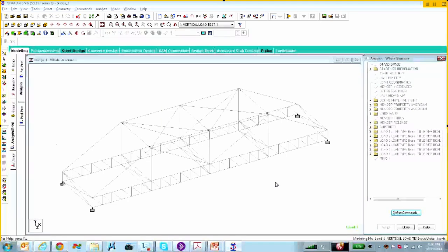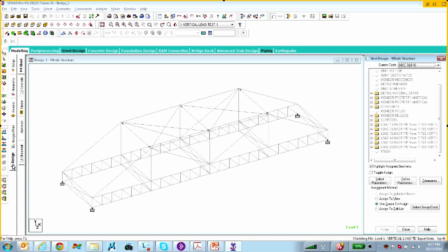So you want to find out if your structure is passing or failing, what your interaction ratios are, and even if the program can do optimization, giving you more efficient shapes than what you initially provided. To do that, our typical workflow in STAAD is, this is our page control over here, and we always want to work our way down. So our last step is design. And you can see here I'm on the Design tab and the Steel sub-tab. And now I have several options for design.